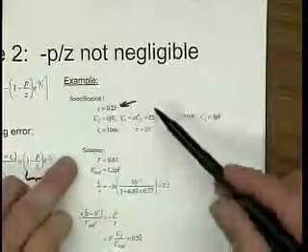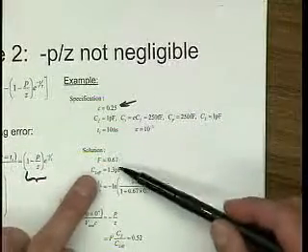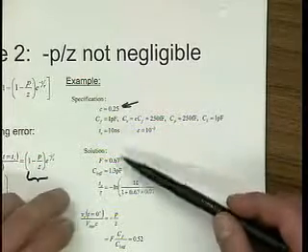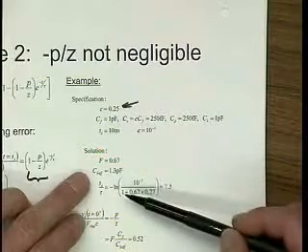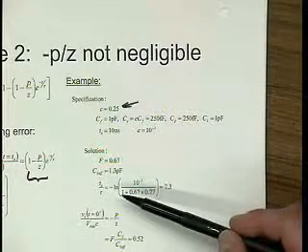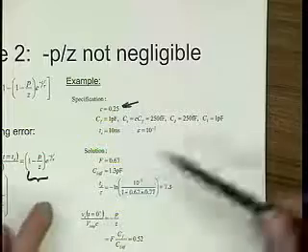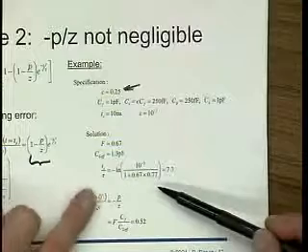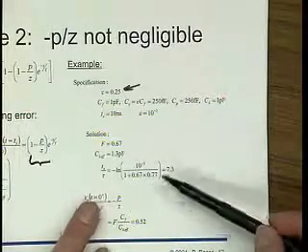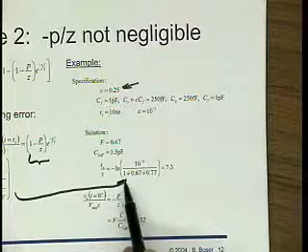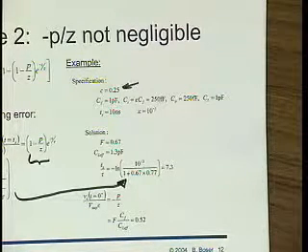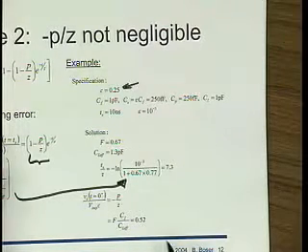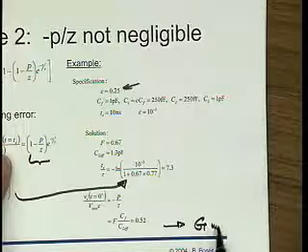Okay, so again we can go through this equation and figure out the feedback factor. One thing that is very nice about this case is that when we generate attenuation with such a circuit, the feedback factor can get very large, very close to unity, and that's what we have here: 2/3. Then the effective load capacitance, and then that's just this here, Ts over tau. So now I need 7.3 time constants to settle, and based on that, again, I can figure out gm. Okay.